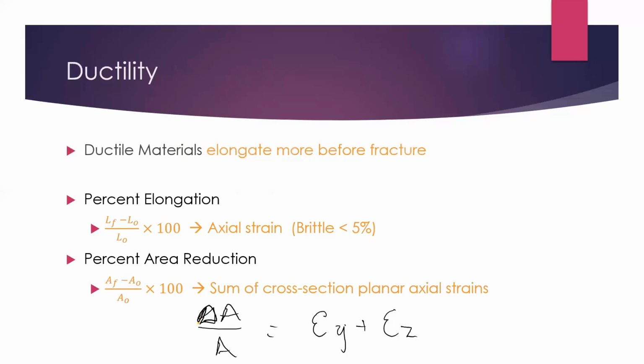So note we only have stress in one direction, but we have strain in all three directions. And why? Do you know why that is? We'll talk about it later, but have you heard of the Poisson effect? So the Poisson effect is the idea that as a material elongates or contracts in one direction, the cross-sectional directions will be affected.